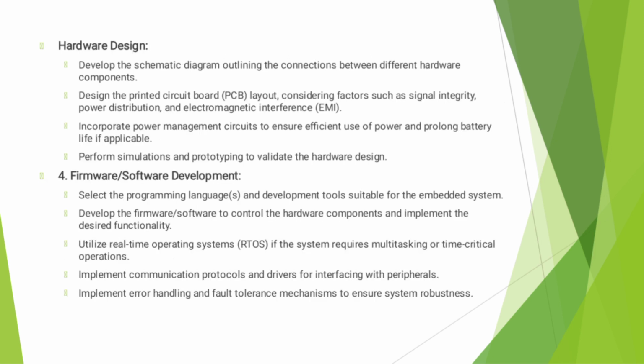Then hardware design. Develop the schematic diagram outlining the connections between different hardware components. Design the printed circuit board considering factors such as signal integrity, power distribution and electromagnetic interference. Incorporate power management circuits to ensure efficient use of power and prolong battery life if applicable. Perform simulations and prototyping to validate the hardware design.